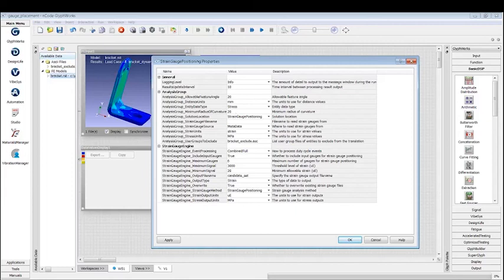In addition, I've brought in a list of nodes that I said you're not allowed to put gauges on. Those are locations around my mounting point for the fixture, as well as the mounting locations for my component that's attached to this bracket, where again I couldn't put gauges because of the fixturing. And then finally, down below, I have specified a max number of gauges allowed to actually compute.